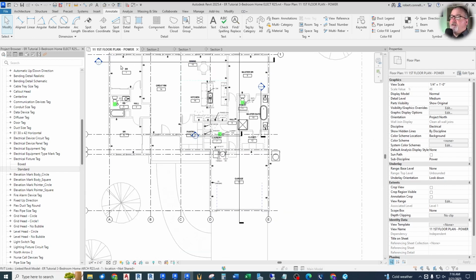Now, the only thing of changing the bottom of the view for the entire plan is that if I had anything else in the crawl space or things like that, it would show up now because I dropped my level down to grade. So if you don't want to change the entire view to a lower level, there's one little kind of an advanced feature I feel like I need to show you, because even in a residential simple basic project, this can easily come to play.